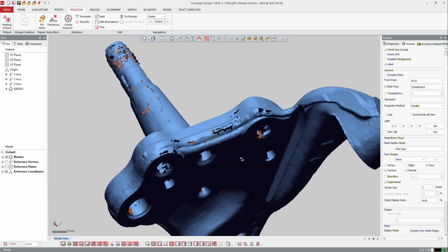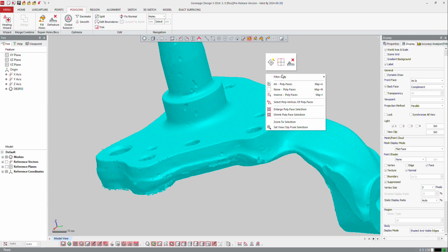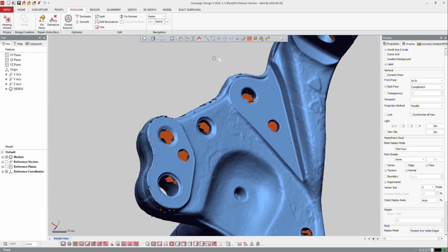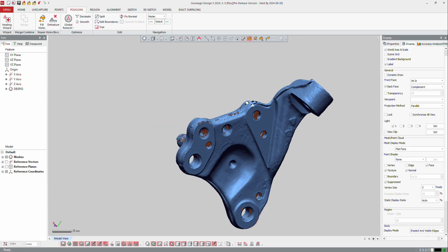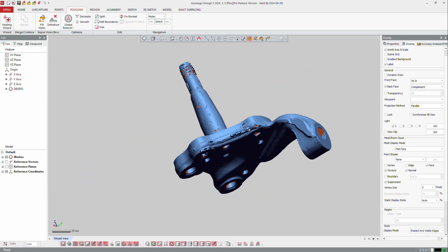So here the software disappeared, so it's okay. I may just use the standard way of cleaning up quickly the part, which is selecting the whole mesh, inversing the selection and deleting the mesh. So like that, I make sure that nothing is connected to that. And I still got some issues on that part. So maybe I need to